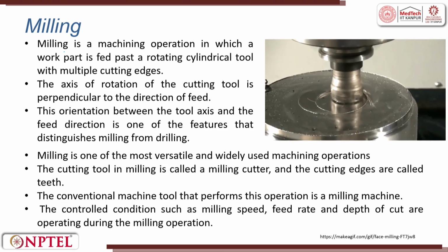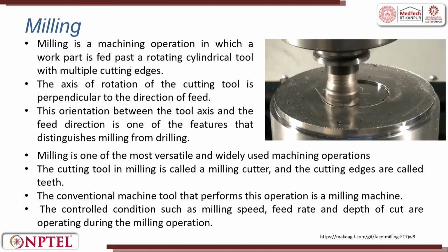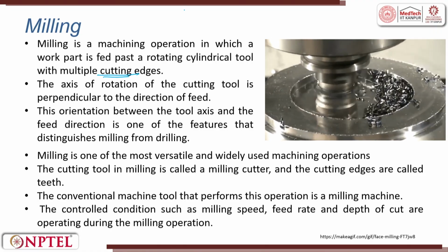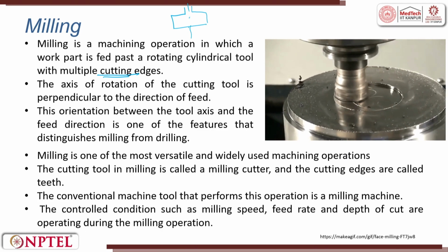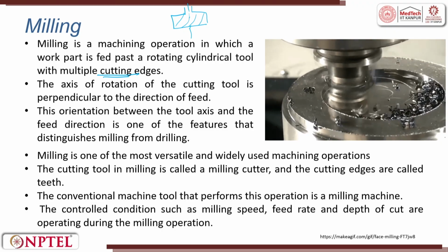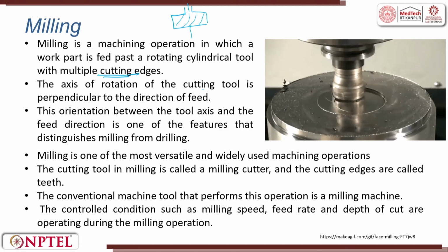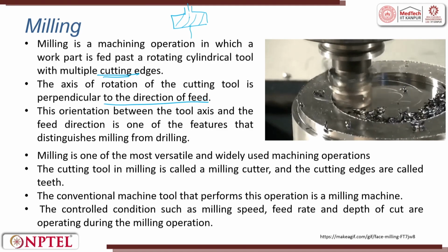Milling is a machining operation in which the work part is fed past a rotating cylindrical tool with multiple cutting edges. So, suppose you have a cutter like this, here you will have multiple cutting edges which are coming in contact with the workpiece. The axis of rotation of the cutting tool is perpendicular to the direction of feed.